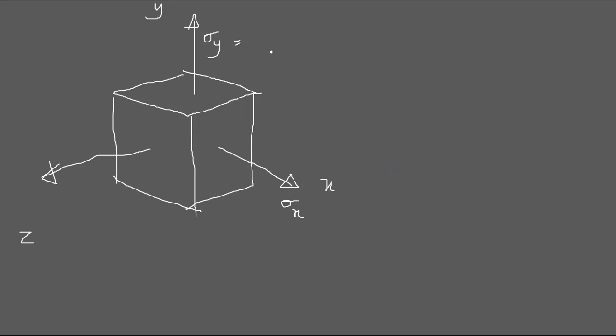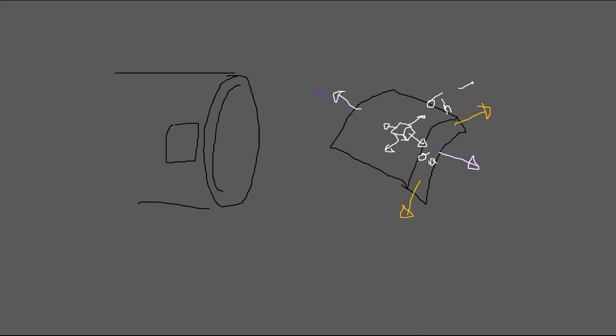And to that, you have to find this stress. So you know the hoop stress is given by this equation, PR over T, and this is PR over 2T. And you have to check this T by R ratio.